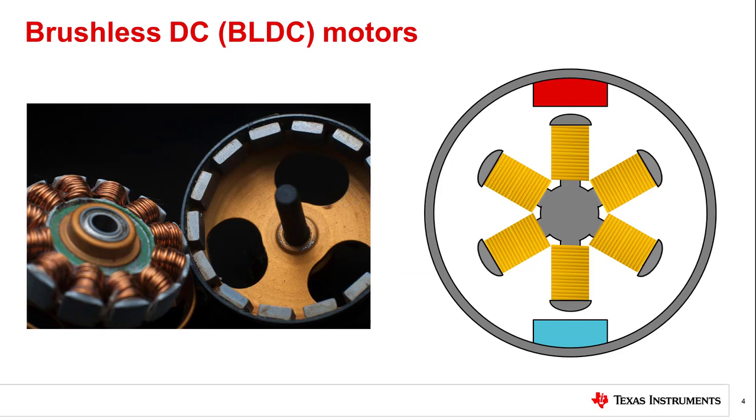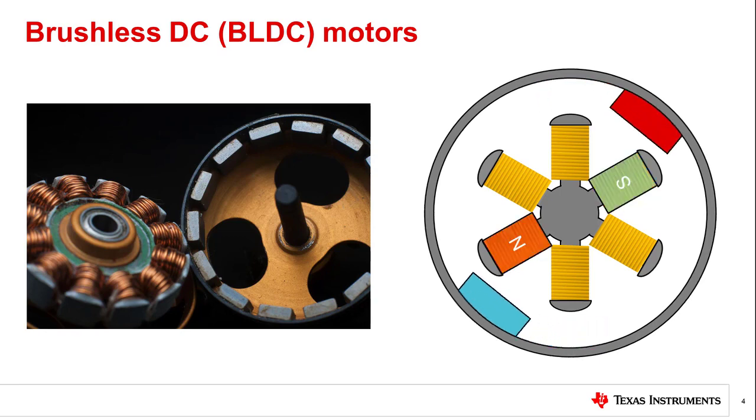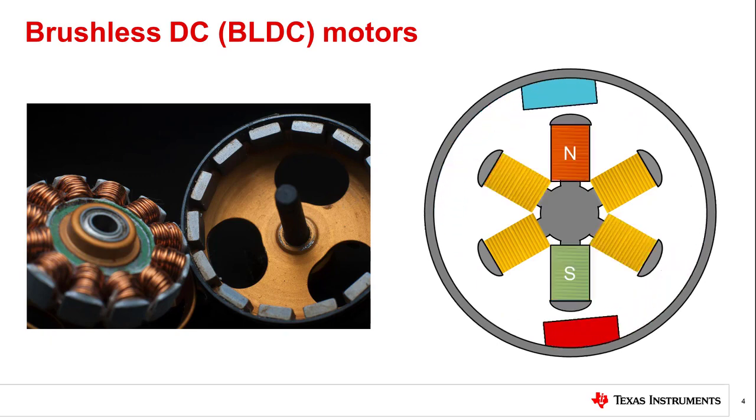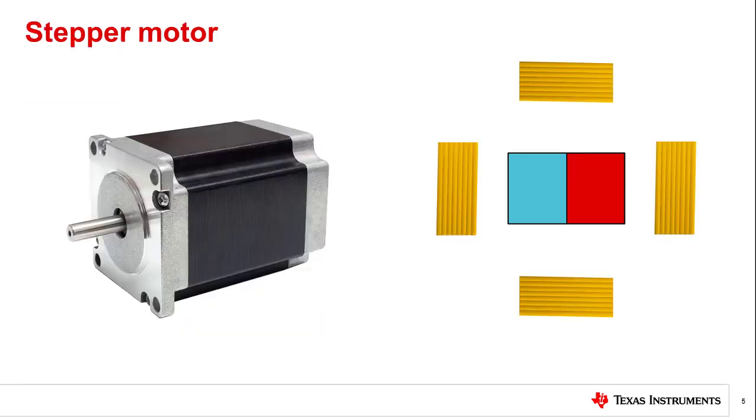The brushless DC motor contains permanent magnets on the rotor and windings on the stator. This is opposite from the construction of the brushed DC motor. For the brushless DC motor, there are no brushes or mechanical commutator. Commutation is handled electrically. Typically, brushless DC motors have 3 phases, which create motion when energized in the correct sequence. The animation and image show an outrunner motor with rotor magnets positioned like a shell around the inner stator windings.